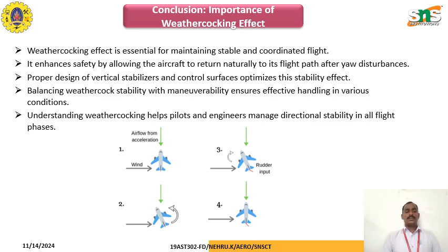In conclusion, the weathercocking effect is essential for maintaining stability and coordinated flight. It enhances flight safety by allowing the aircraft to return naturally to its flight path after a yaw disturbance. Proper design of the vertical stabilizer and control surfaces optimizes the stability effect. Understanding weathercocking helps pilots and engineers to manage directional stability in all flight phases.